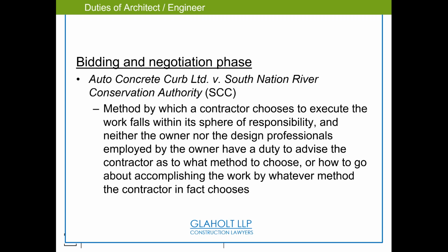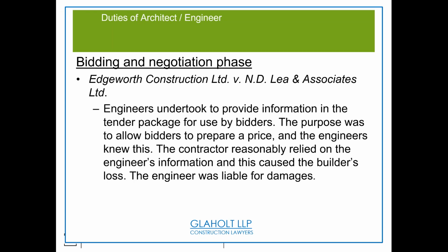So, an example, if in my information model, I show conduit, and the comment is, well, conduit is usually field routed. So if I show it going in this direction on these walls and it doesn't work, I'm responsible. No, the model is advising on a potential method. The contractor could say, nope, I'm going to route it differently. They route it differently, and then they update their model. All good. Very simple.